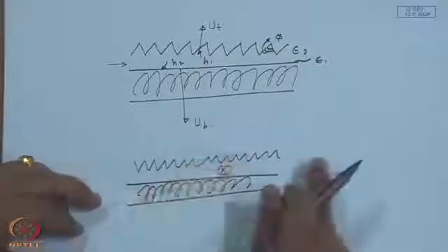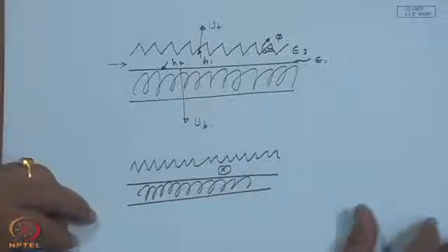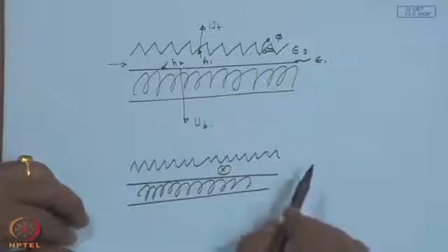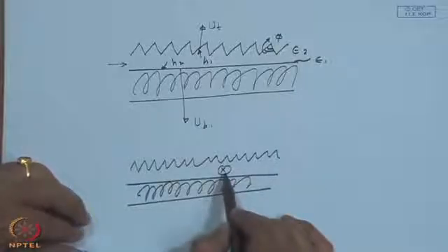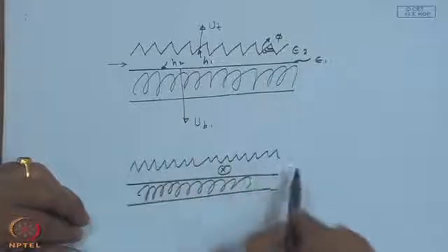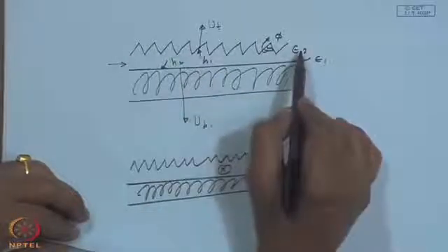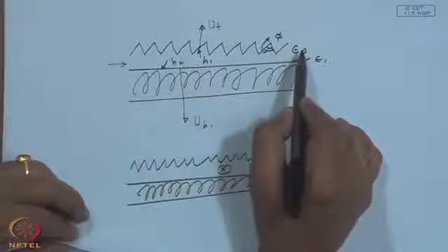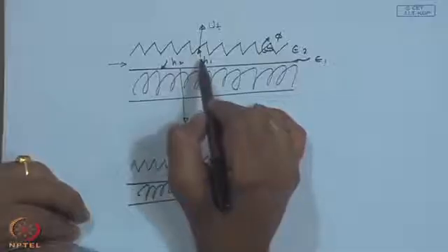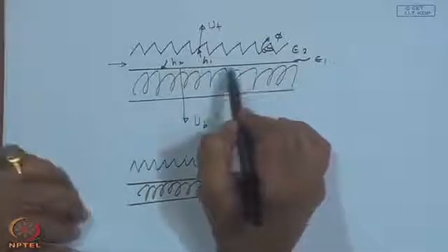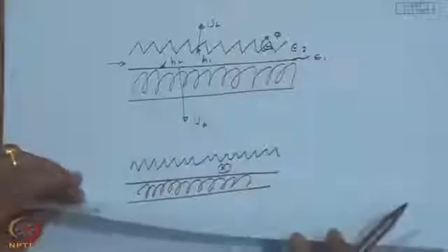Still it has a larger extended area compared to a plain plate. Consequently, it may have better heat transfer characteristics than a simple flat absorber. However, here the phenomenon is different. It aids augmenting heat transfer by breaking the development of the boundary layer as well as providing mixing of the fluid.